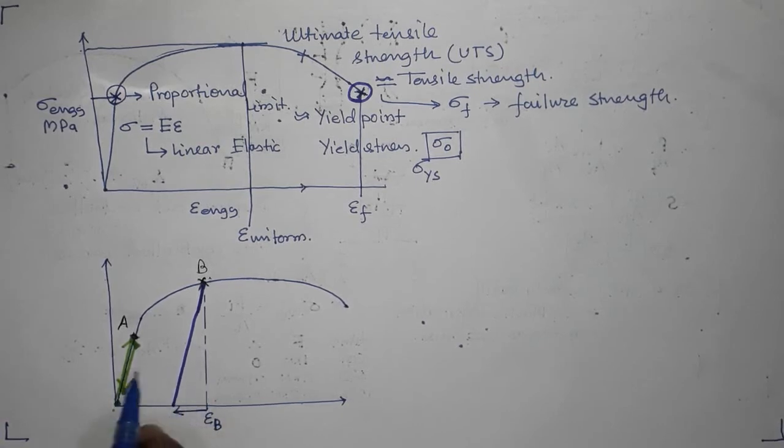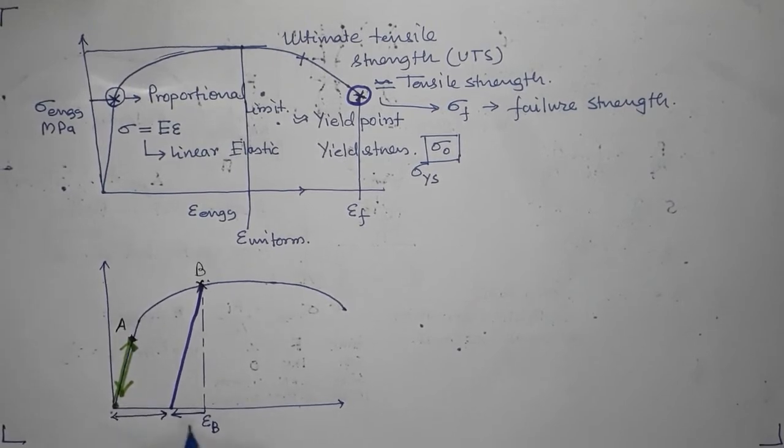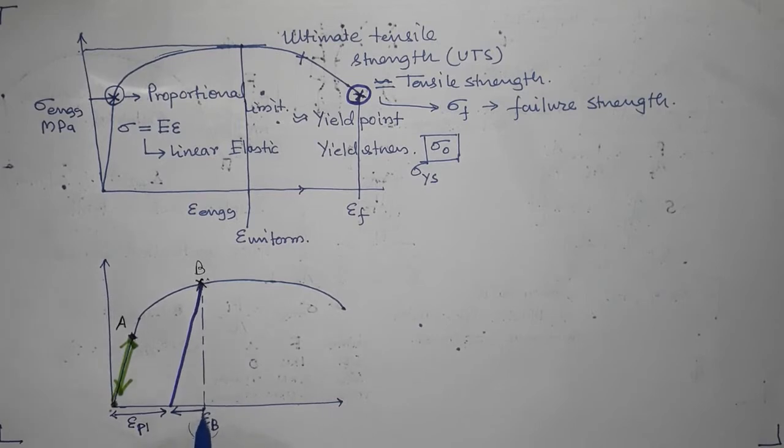There is no temperature dependence, or I didn't do it fast. I did it with the same rate. But even then, only this much amount of strain will come back, and this much amount of strain will not recover. So this is irreversible amount of strain, right? So material is permanently deformed by this much amount of strain, and this is the plastic part of that epsilon B here, and this part